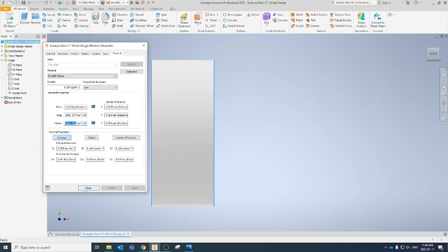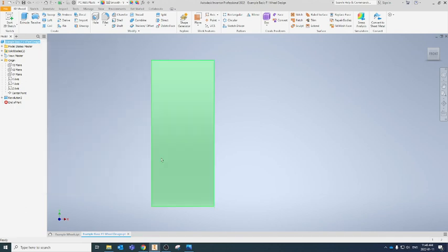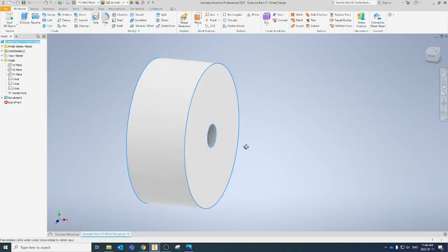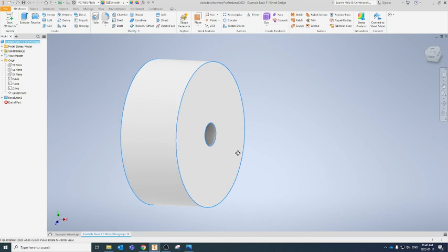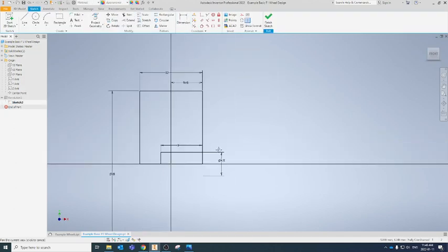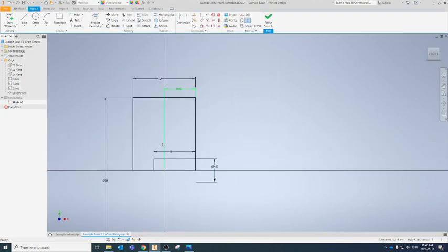Now with our F1 cars, we're always trying to minimize weight because it's very, very difficult sometimes to meet that weight requirement. So one way we can minimize weight is in the wheels, by doing some cutouts or some profiles on the front and back of our wheel here. So let's jump back into our sketch. I'm going to go into my sketch again by double clicking on it, and let's make some changes.